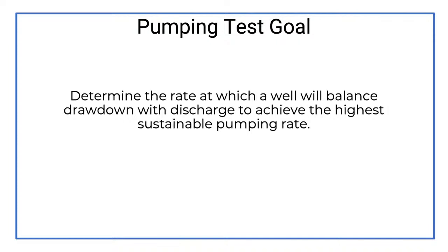Other purposes of the pumping test: we can develop a lot of our aquifer properties from directly measuring our pumping test parameters. Hydraulic conductivity is one; transmissivity and storativity are some of the big ones we can directly calculate from pumping tests. And also we'll use pumping tests when we've done a rehab on a well, we've cleaned it up, to see what our capacity is after we've cleaned it up, and reestablish that going forward. So a lot of different goals for pumping tests, but our main one after we build a well is to determine what our maximum sustainable pumping rate is.